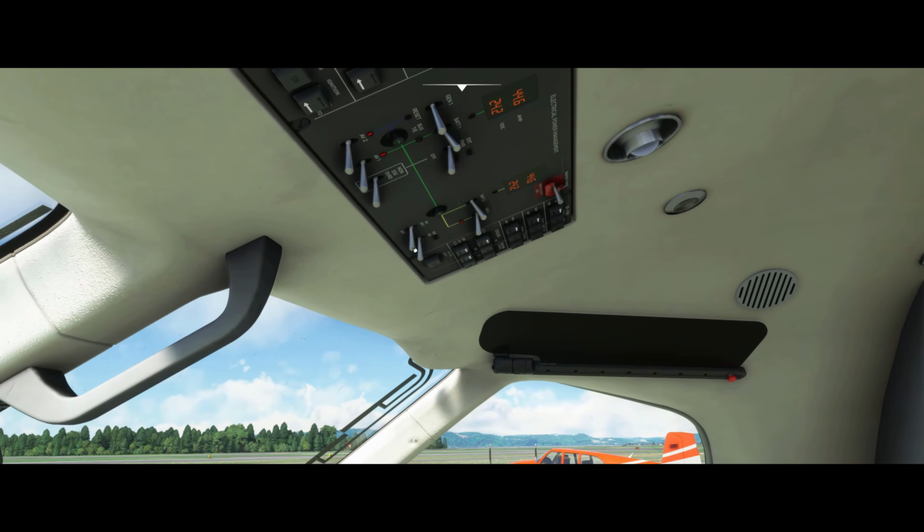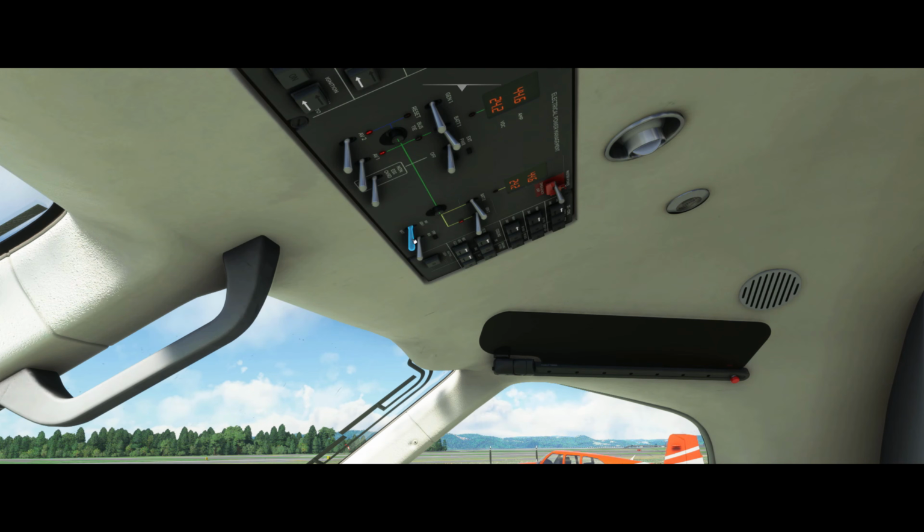And then our inverter we would switch. There are 2 inverters on the airplane, one on Gen 1, one on the BAT. We just switch it each time so that the inverters are getting even wear, so it doesn't really matter. There's no operational difference between the 2. We just cycle at each flight so that they're getting even wear.